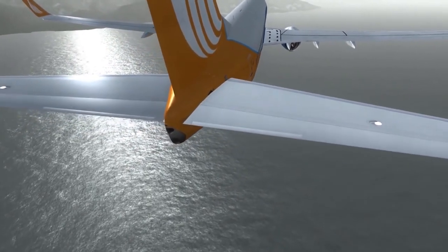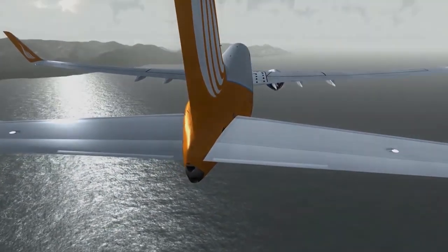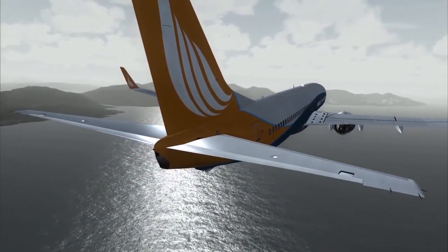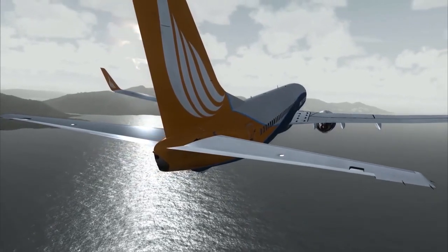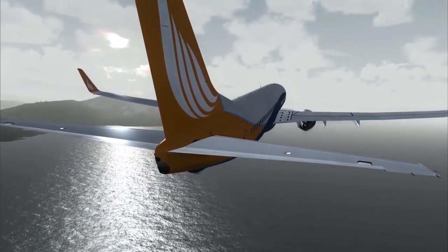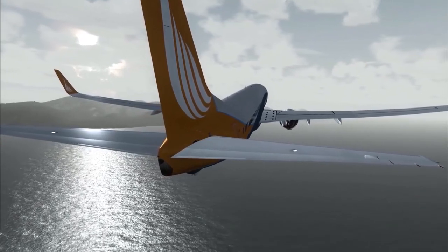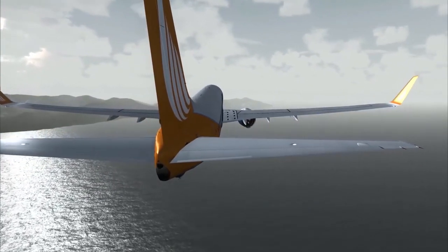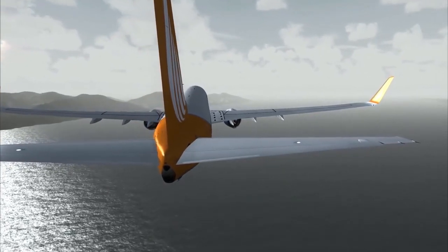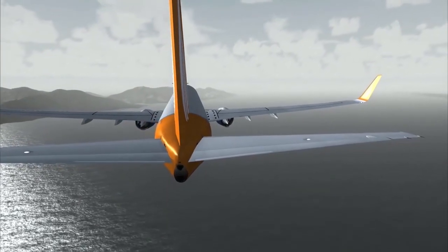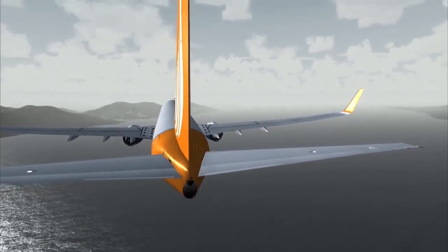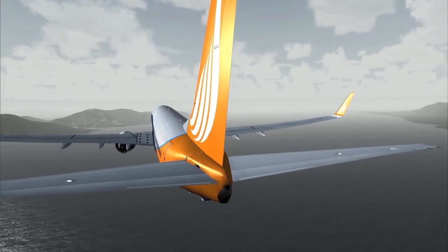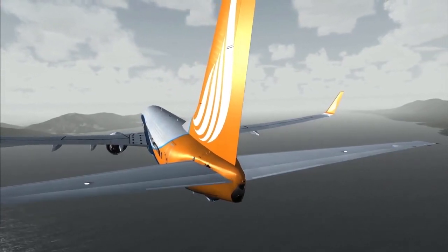When the horizontal stabilizer is neutral and there's no input to the mock trim actuator, which will be discussed further along, the elevator is downrigged 4 degrees, with reference to the stabilizer mean chord line. From this position, the elevator can move 24.3 degrees up and 18.1 degrees down. Each elevator has 3 balance panels, with balance weights in the forward side and a tab attached to the aft edge. The balance panels decrease the force necessary to move the elevator in flight.